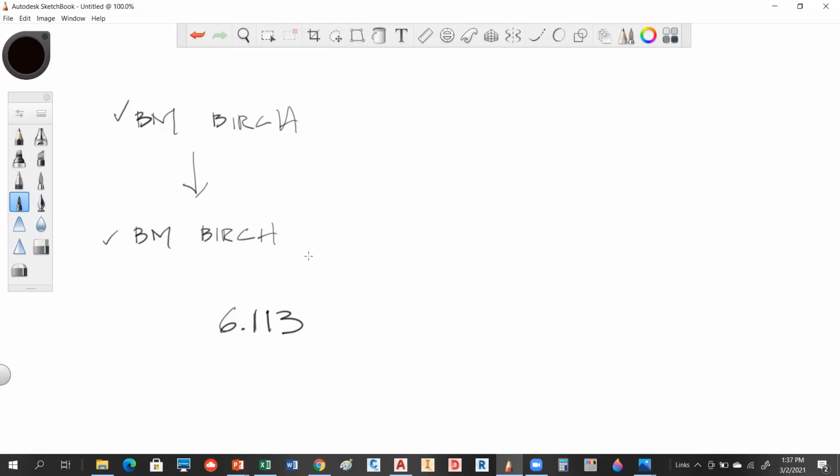But my initial question: Shelley, you told me you had a misclosure. If you sum your backsights, I came up with a plus 0.006. Is that what you get? Yes. Okay. So this has a pretty tight misclosure, so it could be a precise level loop, because that's the kind of work those guys would be dealing with. So check these notes out. If you haven't had a chance to do them, look at them. If you have any questions, submit them to me.